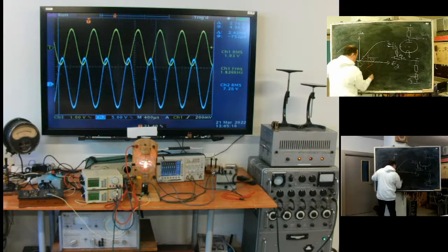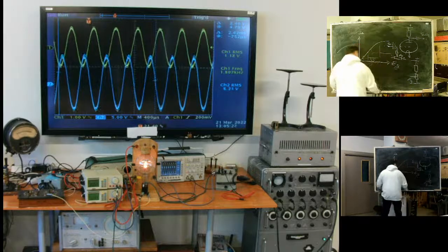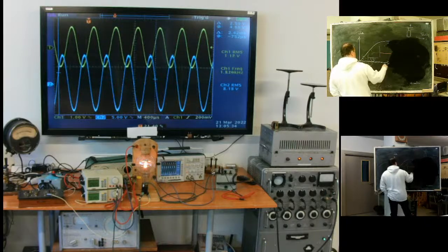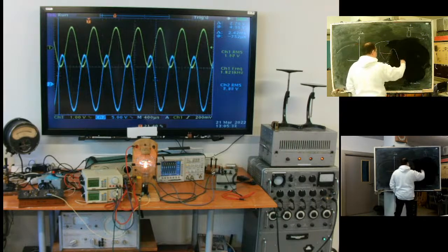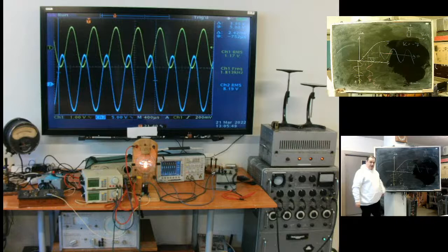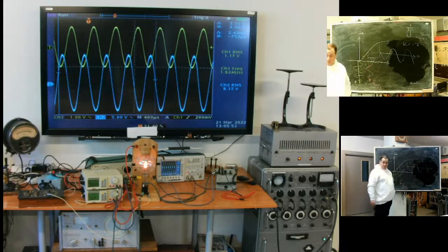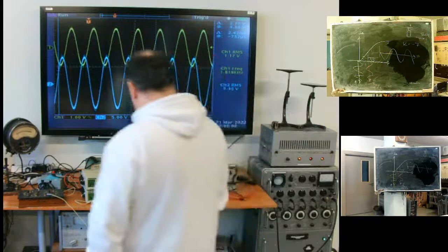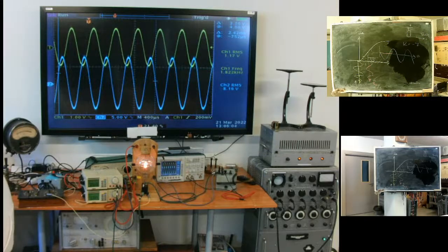Input. This again is axis as time. Output will be what we will see. Amplification, but it will be negative. Amplification, but with negative sign. We have a system with a factor of approximately -7. It's linear, it amplifies, but inverts. Yes, it's normal for an amplification system on a single stage to invert. So we got a linear system.